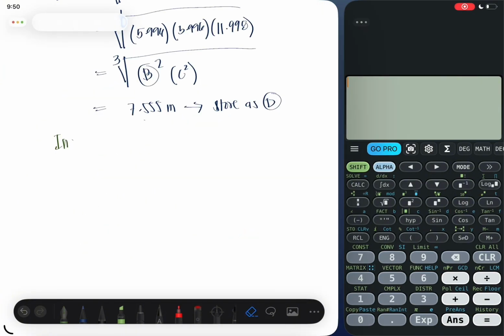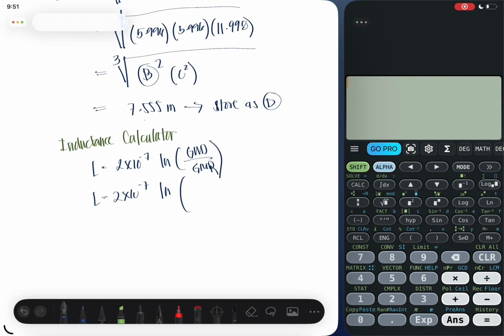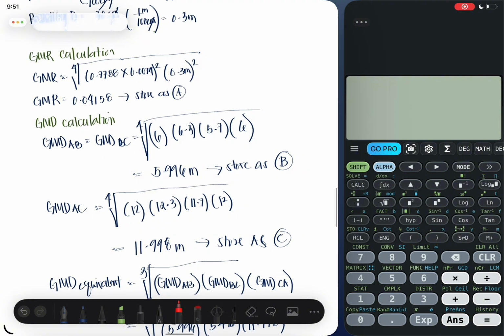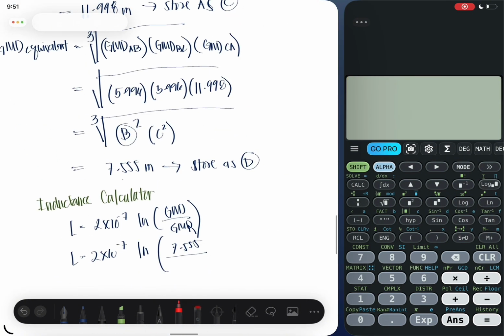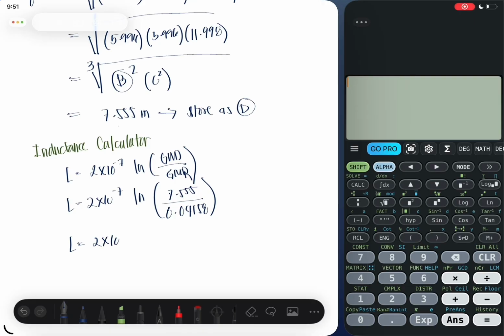To calculate the electrical inductance of a transmission line, engineers rely on the physical layout of the system by combining two mathematically simplified values, geometric mean distance and geometric mean radius. The total line inductance is calculated by dividing the uniform equivalent distance by the effective radius, taking the natural logarithm of that specific ratio, and multiplying the result by a standard physical constant.